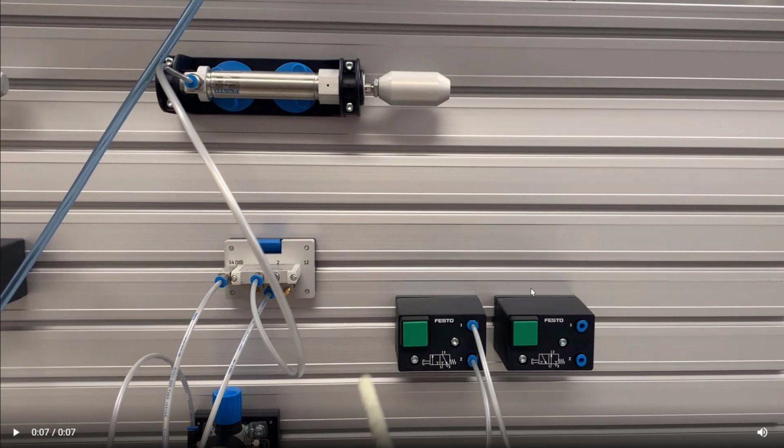I'm going to pause that. We're not using this push button. We're only using one push button. This guy is a DCV with a spring in it. So we've got a pilot activating the DCV and then a spring return or a spring normal. So it has the normal state because it's got a spring. And this cylinder, it's got a spring in it too. It has to have a spring in it.